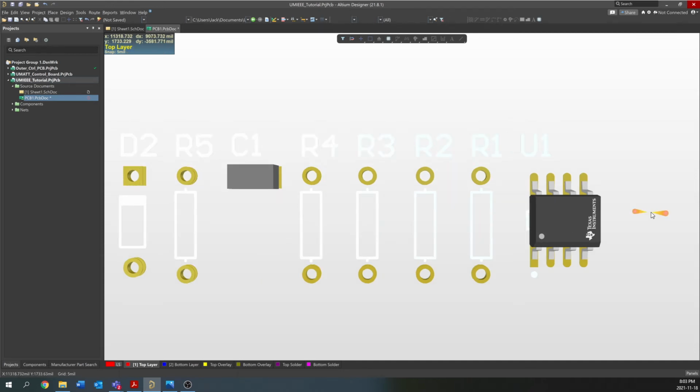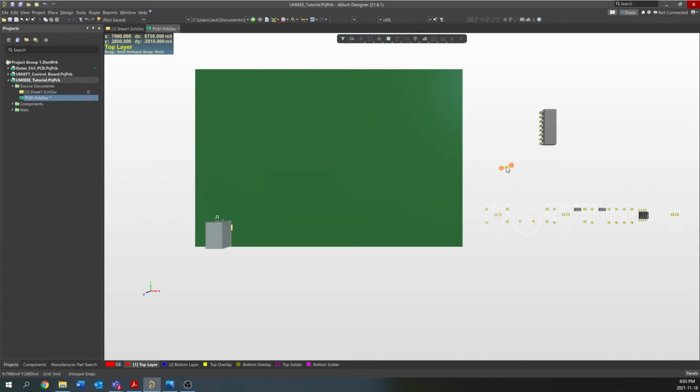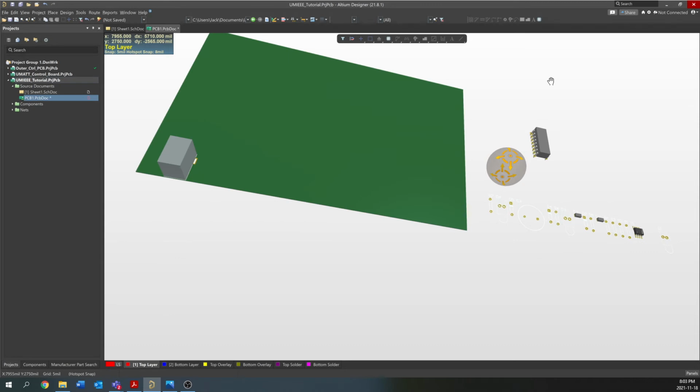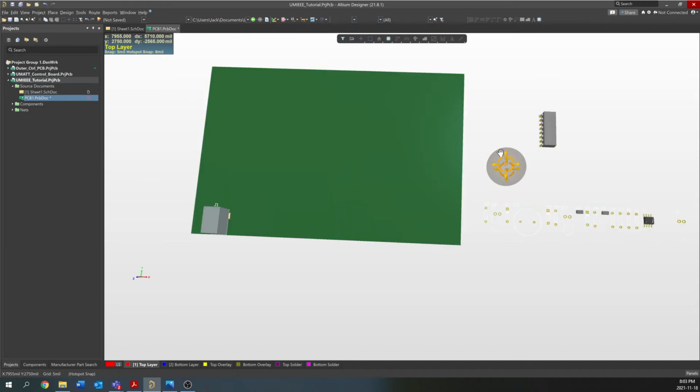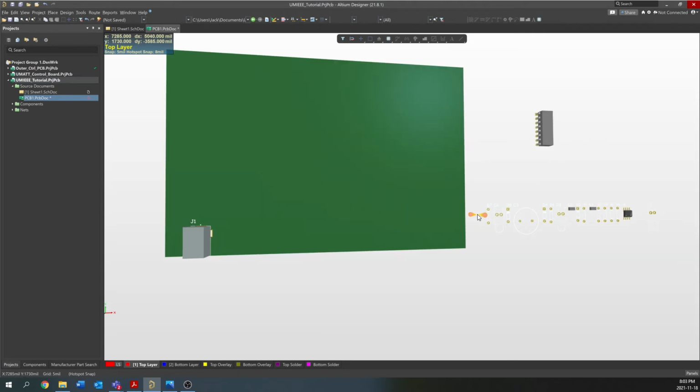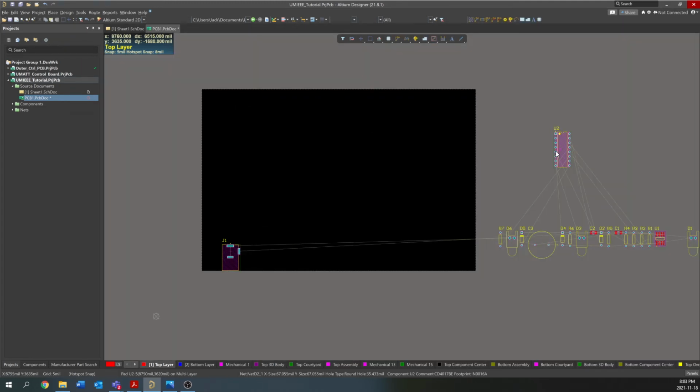You can move around in 3D mode by holding down Shift and left clicking, which allows you to actually turn stuff around and get a visual. And you can, again, scroll, Control scroll, and Shift scroll for the different up, down, in and out viewpoints. So go back to 2. You can only see it flat on in the 2D mode.